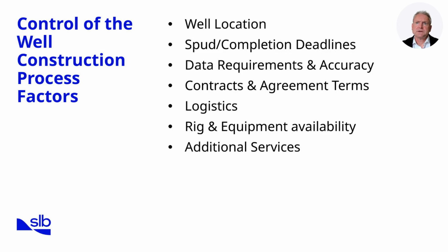The rig and equipment availability is another controllable aspect, where early planning and clear specifications help avoid operational bottlenecks. Finally, we must account for additional services such as wireline, mud logging, or well testing, all of which must be integrated into the construction plan. While subsurface conditions are uncertain, the way we plan and execute construction is very much within our control. Next, we'll turn to the elements that are not controllable.